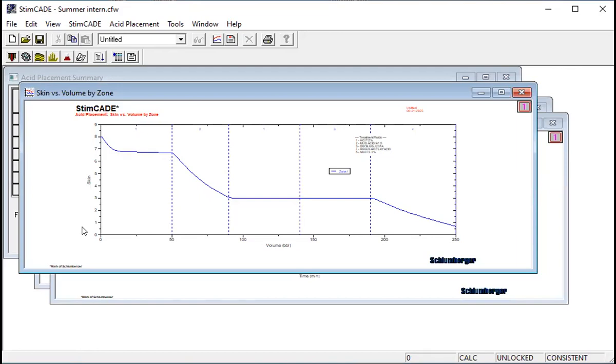During acid treatment, it is not a must that you remove everything. It may be impossible to attempt to remove everything. That's the reason why in most cases, you may not have a negative skin like in hydraulic fracturing. Because in hydraulic fracturing, we are sure that once we have created the fracture and used our proppant to block the fractures from closing up, we should be able to have high drawdown or high production. And that should be able to give us a negative skin.